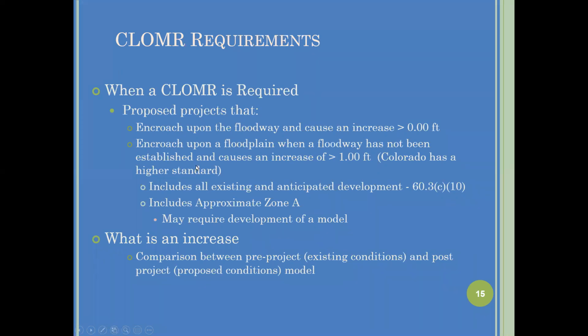What is an increase? There are several analyses required when doing a CLOMR. You'll be comparing the effective information, but that effective information may not reflect existing conditions. So when you're doing your comparisons, you're going to be comparing a corrected effective or existing conditions model and the post-project conditions model.